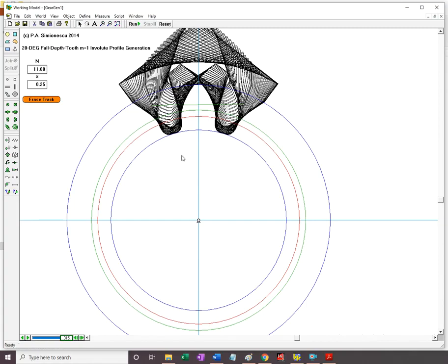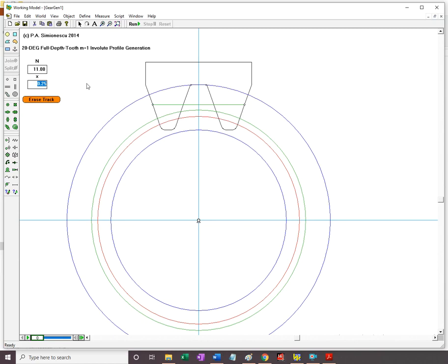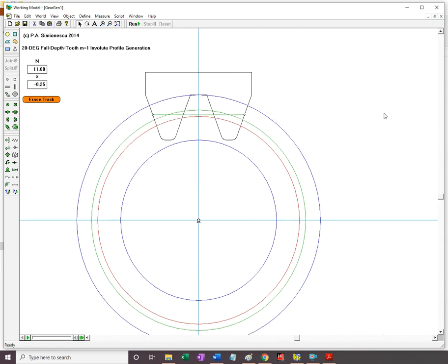So if you want to go with fewer than 17 or 18 teeth, which is assumed to be the minimum number of teeth of a pinion or a gear, the undercut is acceptable and it could operate. If you want to go less than 17 or 18 teeth, you need to consider an addendum modification of positive type. If I instead make this number negative, I exaggerate the undercut.